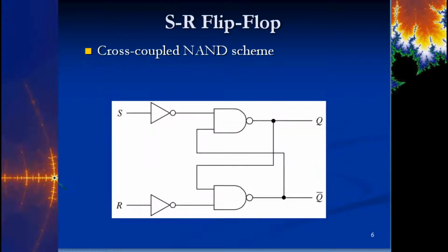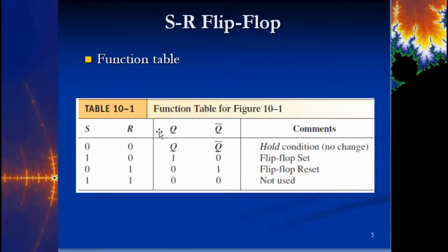With the cross-coupled NAND, you have two inverters out front before it reaches the gates, and Q is on top here. Okay, so just remember that if you have to draw these for me. Okay, but you can construct either one with these simple gates, right? You don't need to buy an IC chip for it. It's a lot easier if you do, but you could create a data storage circuit using just the basic gates we've learned so far.